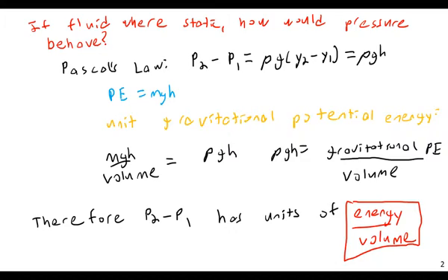If you remember back from your study of electricity in your physics courses and electrical circuits courses, the way I think of pressure is, if I say volumetric flow rate is equivalent to electric current, then pressure would be equivalent to voltage. Pressure is kind of equivalent to voltage in an electric circuit; in a circuit of fluid, the analog of voltage is pressure. Pressure really represents internal energy.